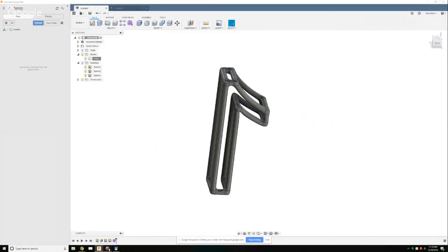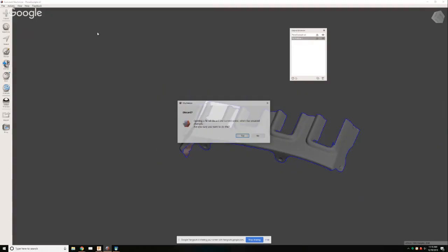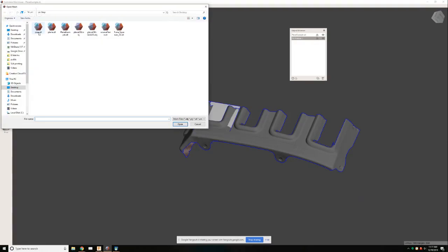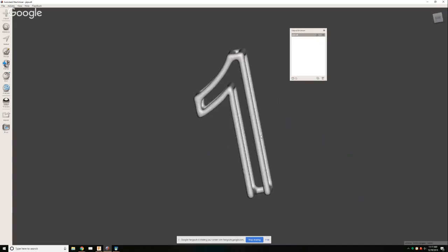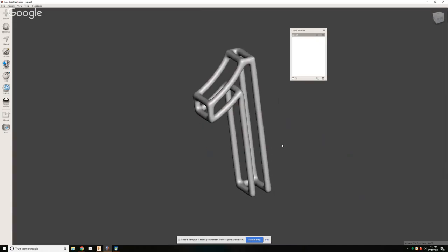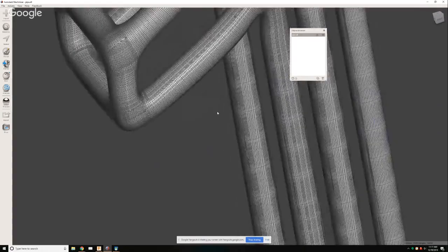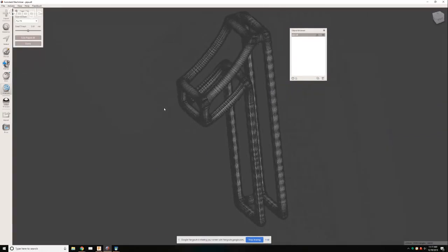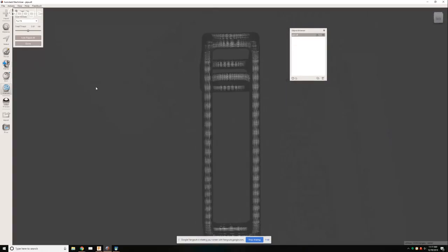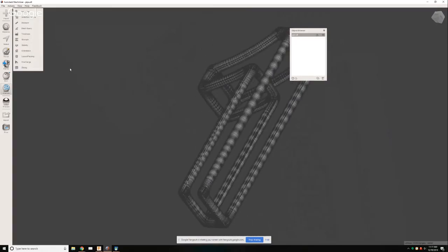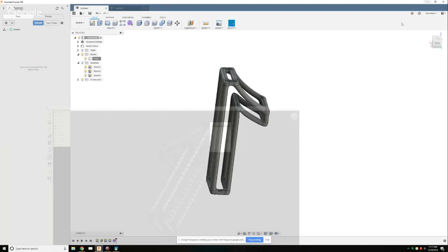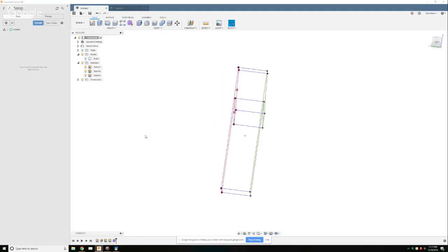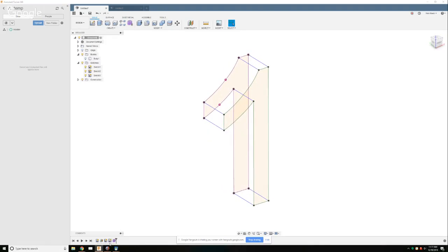And if we open this up in Meshmixer and import the pipe, we can see that we have a full solid body. Oh, it looks like I missed one down there. But if we hit W, you can see that this is just a full thing. It's all ready for 3D printing. We go to Analysis to Inspector, no problems with it. Fully ready for 3D printing. And you might need some support material, but it is a pretty cool workflow that you can use all inside of Fusion that is all just based on blocky sketch connections with each other.